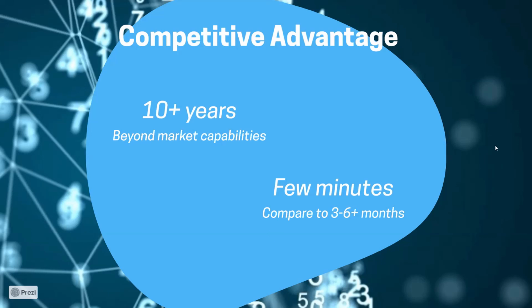In history matching, our biggest advantage and our predictability is that we can do it in a short time. We can do it in a few minutes, rather than with a lot of these modelings, especially once you get to the wellbore and you want to put in nonlinear completions such as FCD, where it takes months and months. It's not just days, especially for thermal applications, because they have a lot of convergence issues. Even if you fix those, it takes a very long time, more than 3-4 months to get something meaningful.